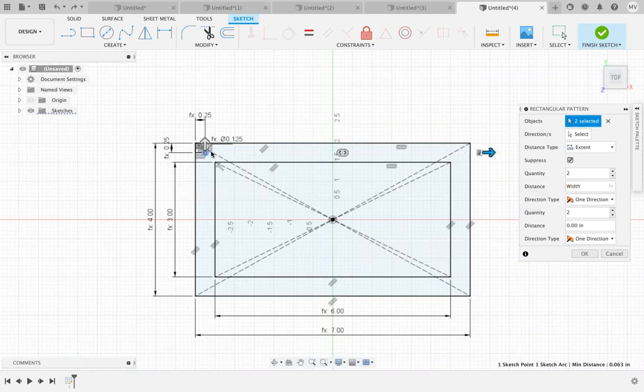Notice I'm a little past the edge. This checkbox is where the circle is going. I'm past the edge here. How far past did I go? Well, width is from left outside to right outside. This hole is shifted by half of the thickness. So I'm half thickness past the edge. I really want to be earlier by half thickness. That would put me on the actual edge.